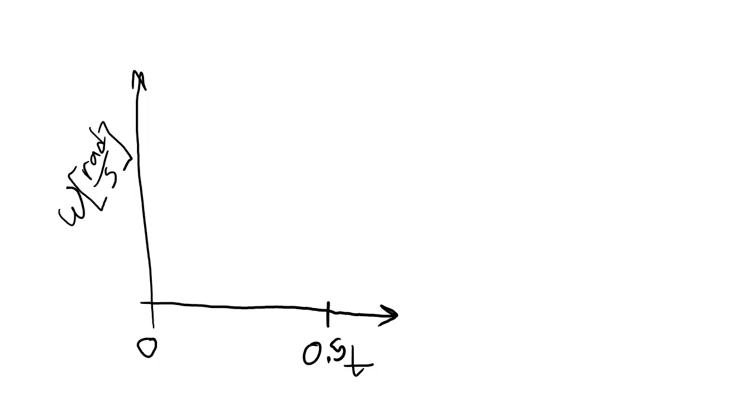The reason I've drawn the y-axis as being the rotational velocity is because from a plot of rotational velocity, I can get both the acceleration and the displacement, or the amount of distance moved during this move. The displacement will be the area underneath the curve that I draw here, and the acceleration is going to be the slope of this curve.